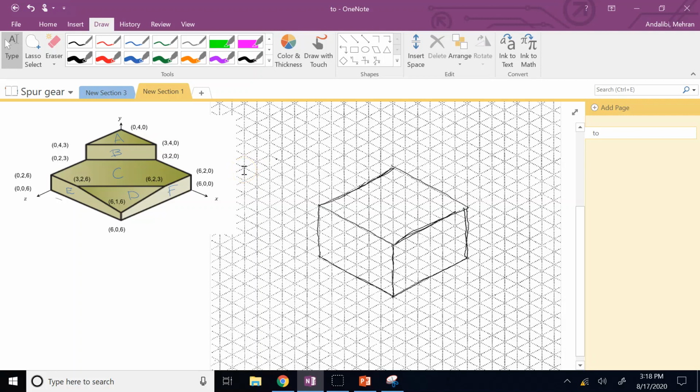And then you want to start with one of these. Which one is the easiest? The one that is touching the bounding box. A is on the top surface, E is on the front surface, and F is on the right surface. So any of them would do the job. So if you look at A, that corner of it is this top corner. And then if you look at the units, so you're going from 040 to 043. So the only coordinate that is changing is this guy. So it's 3 units.